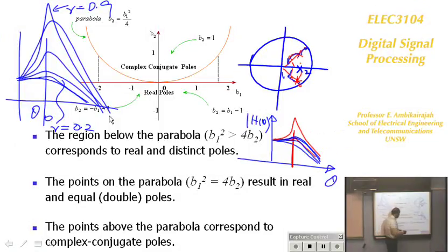What does that mean? That means I am going to move these poles there. They're going to be on the unit circle. They are resonant poles, they are on the unit circle. If you have it here, on the real circle, there's no good here. There's not much use to you. It's still stable, but it's no use to you. But here, if you have got a resonance on the unit circle, then it becomes an oscillator. That's the next chapter.